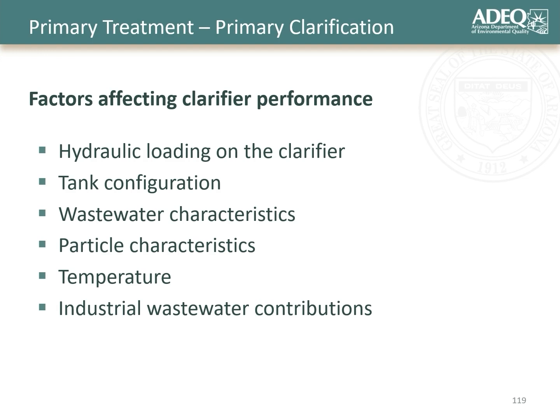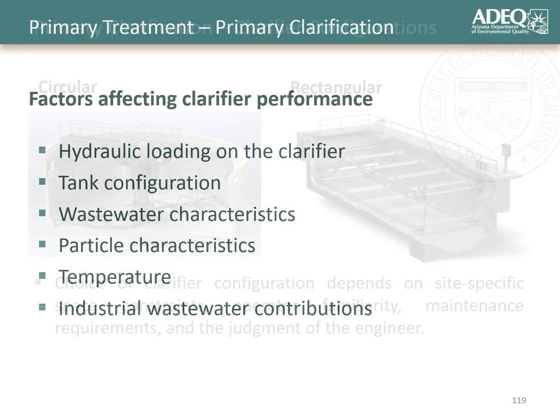And lastly, if you happen to have an industrial wastewater discharge that has a lot of soluble BOD, that soluble BOD is not going to be removed by your primary clarifier. As a result, if you look at BOD removal performance, the clarifier is not going to look great. So there are a couple of things that you want to think about in terms of what could impact your system performance.